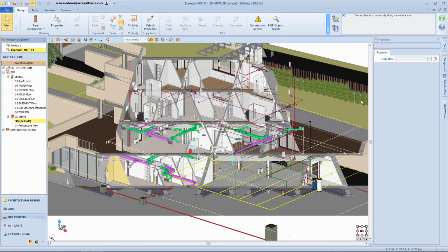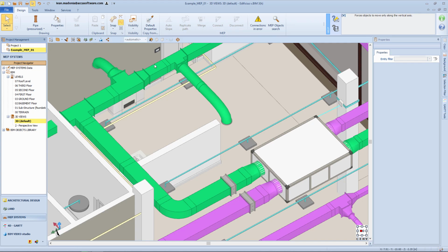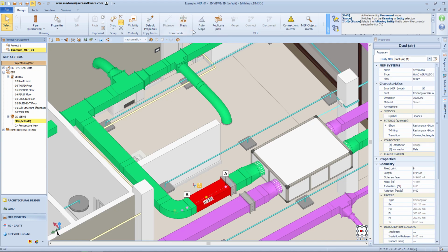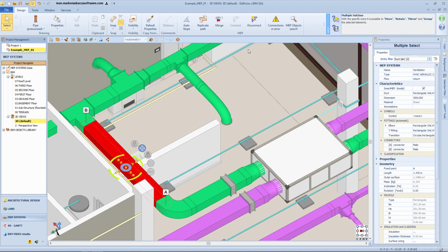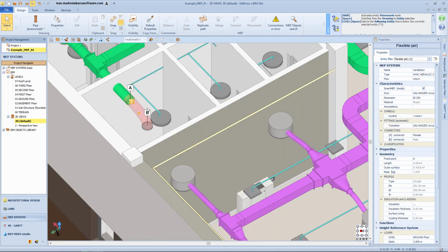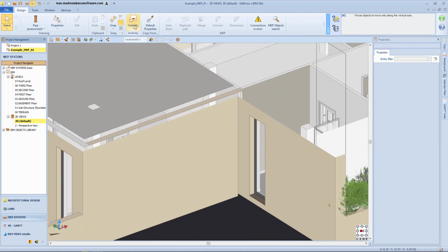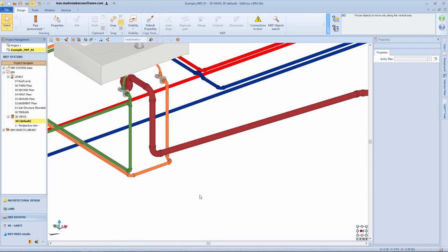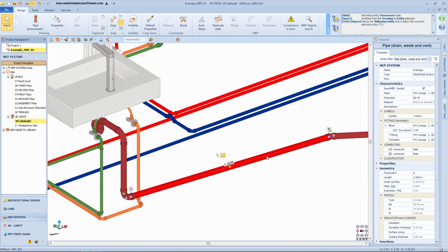In the MEP environment, the upper drawing toolbar includes, among others, the MEP section, in which support functions are available for tracing the connection entities. These options can be activated, depending on compatibility, for all rigid connection entities, relating to both mechanical and electrical systems, therefore pipes, ducts, cable trays, and walkways, while they do not apply to nonlinear connection entities, such as flexible and corrugated. The first available option is automatic slope and can be activated if you select a section of pipe that is not perfectly vertical on the drawing, with the aim of repositioning the elements to create constant slopes.